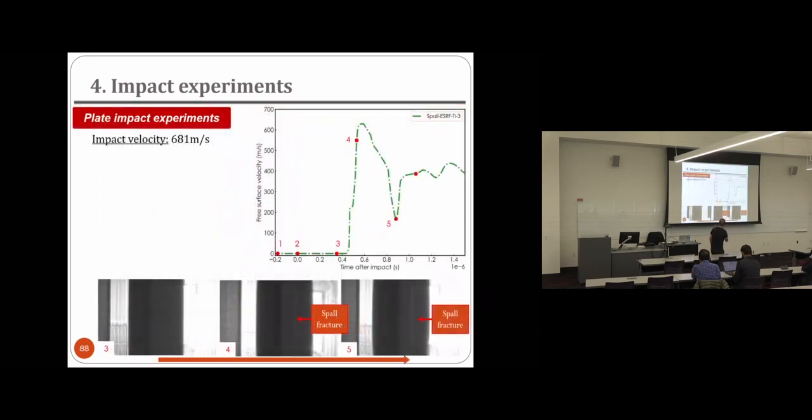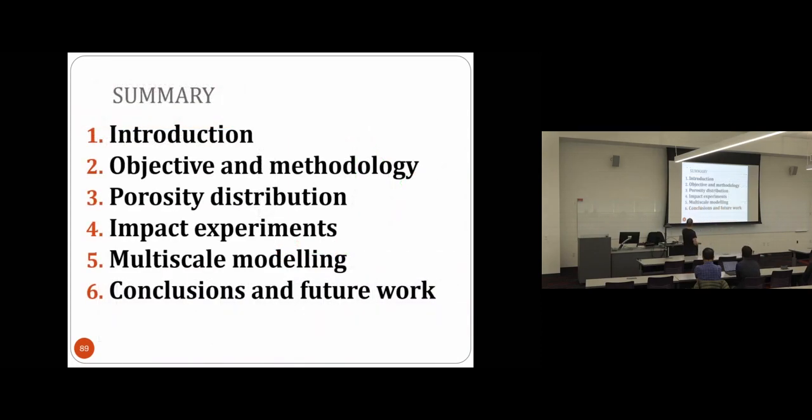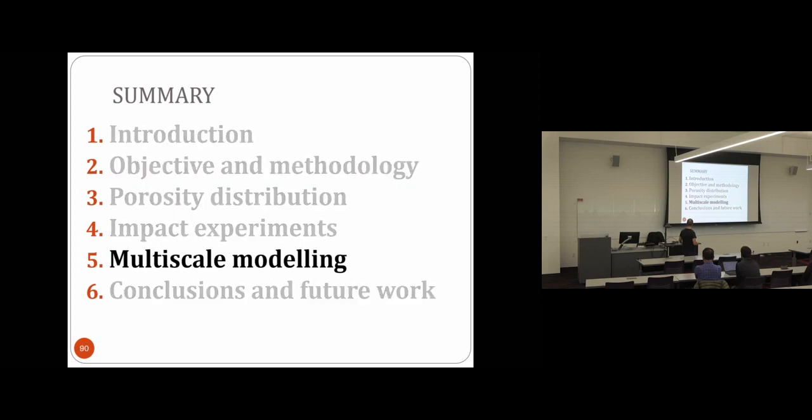And once again, we have the loading time because we have the PDV system, which is synchronized with the cameras. So we can relate the free surface velocity, the PDV signal, with the formation of a spall fracture. And I think I will stop here, as I was afraid that I was not going to have time for showing the multiscale modeling, but I think the experimental part was nice. So thank you very much.